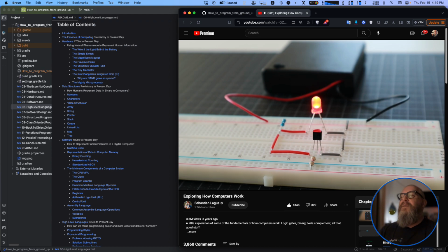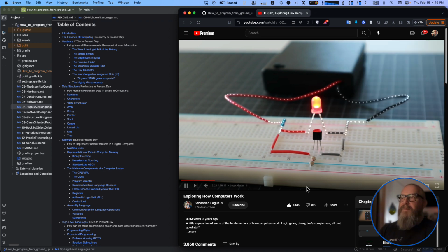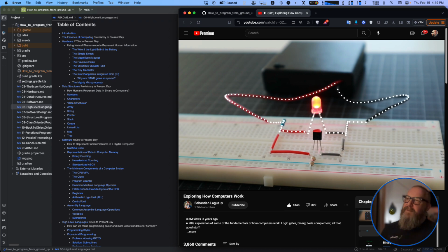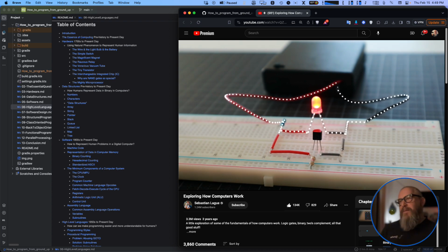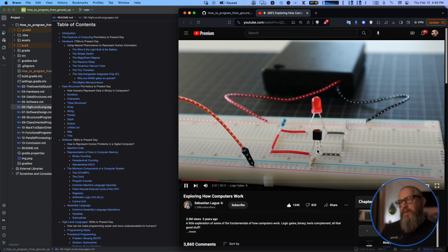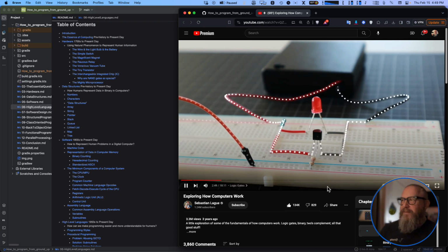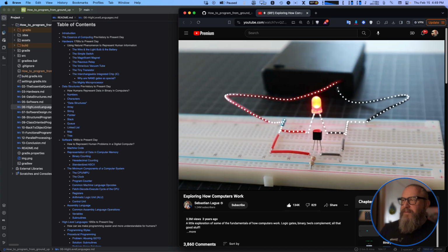As a tiny example of what transistors do, this is essentially that same NOT thing from before, just set up on a breadboard and with a transistor in the place of the paperclip switch. If we think of the current flowing in the circuit, it would look something like this. It can't flow through the transistor at the moment because right now it's acting as an open switch. But if we send power to the middle pin of the transistor, establishing a small flow of current like this, the fancy physics of the transistor will make it act like a closed switch instead, allowing the main current to flow through it like so. Just like before, the light is turned off because we've created a much easier path for the current to take. So essentially the transistor is a switch, which we can open and close with electricity instead of our fingers.